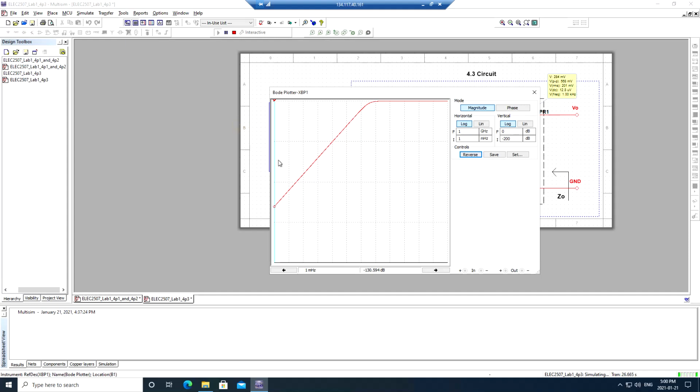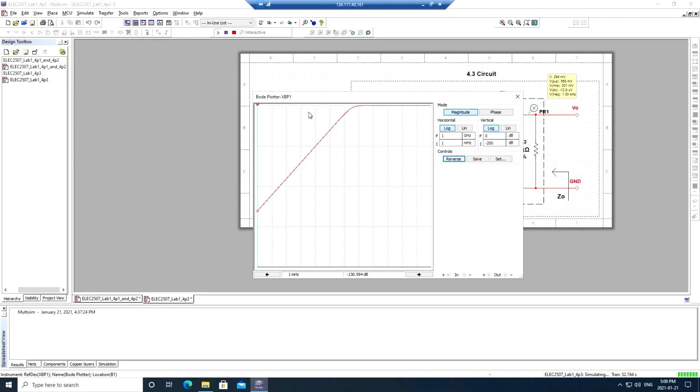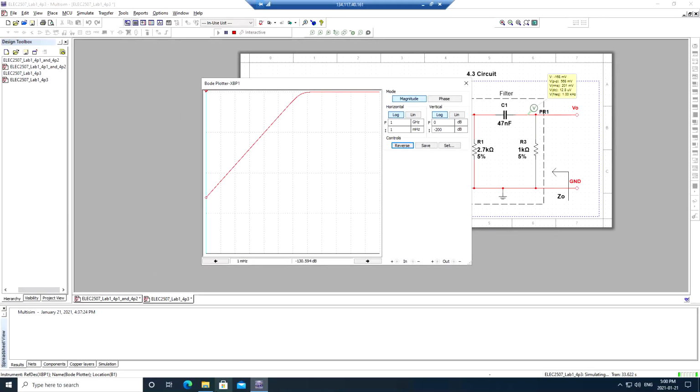So the smallest value is actually 1 millihertz here. You're going to have to extrapolate backwards and find out what the gain in dB and what the theoretical phase difference would be at 0 hertz. There's no actual tool that can measure at 0 hertz, but it's a theoretical gain and phase that you're going to have to calculate there.